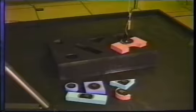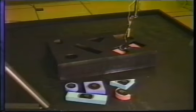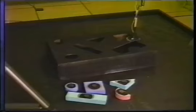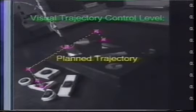During transportations, one feature is tracked in each camera. During fine manipulation, full object pose is controlled by tracking several corners. Once aligned, the piece is inserted. The estimated model is used here also, but now open loop, without visual feedback.